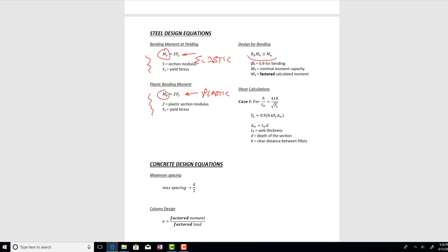This equation right here is by definition the LRFD equation. On the left side of the equation we have our failure, and remember we apply a factor that reduces failure, and then on the right side of the equation we have our loads that we anticipate, and remember we throw factors on that increase those.